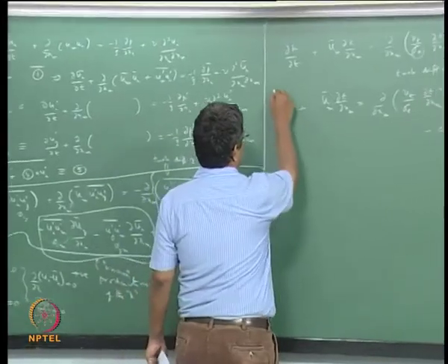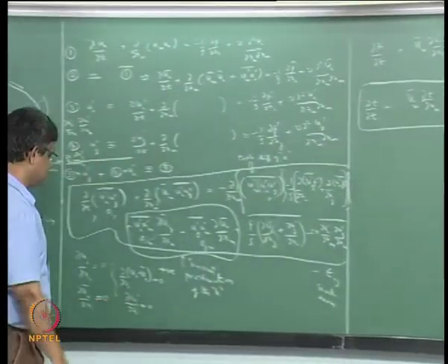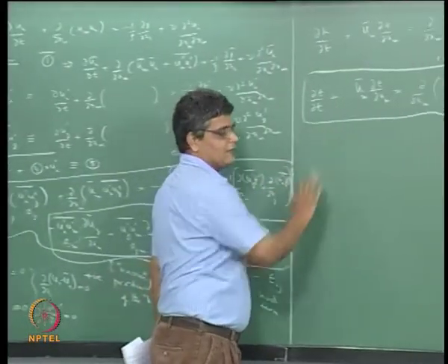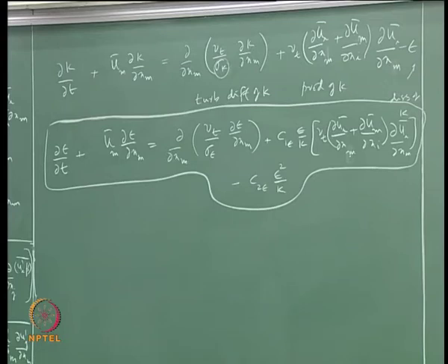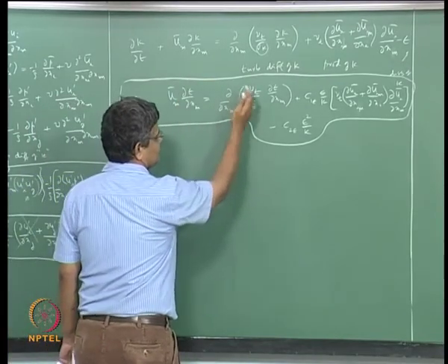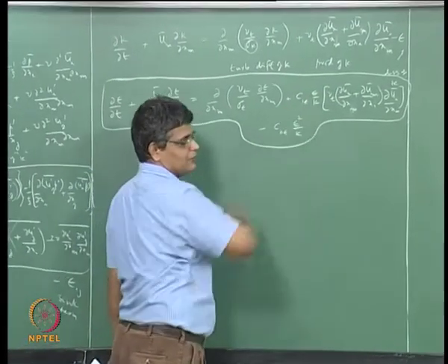So this is the modeled equation for epsilon, and that is the epsilon equation that we are talking about. So this is only loosely and roughly derived from the exact Navier-Stokes equations with a lot of approximations and simplifications. And when you look at the additional equations that we have to solve, we see that these are of the standard form, generic scalar transport form, with an accumulation term, an advection term, a diffusion term, and production plus source and sink terms put together.